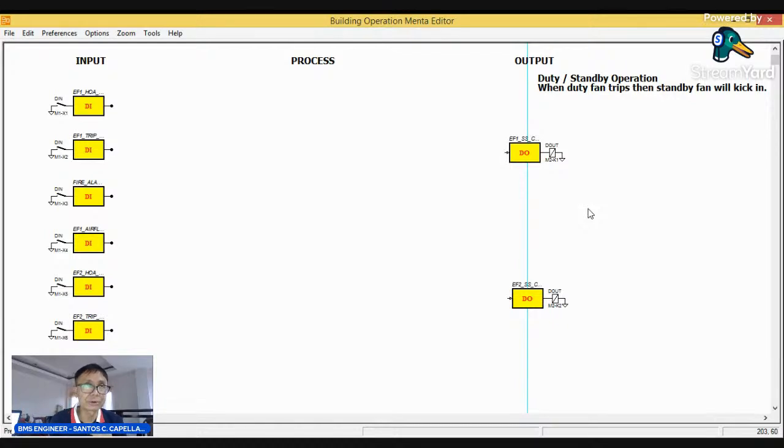But for my side as a BMS engineer, I need to stop it also when there is fire, because let's say the fire alarm relay module installed in the motor control fails, then my system can also stop the equipment during a fire scenario.